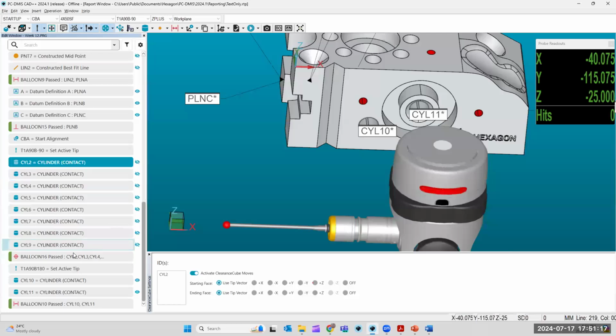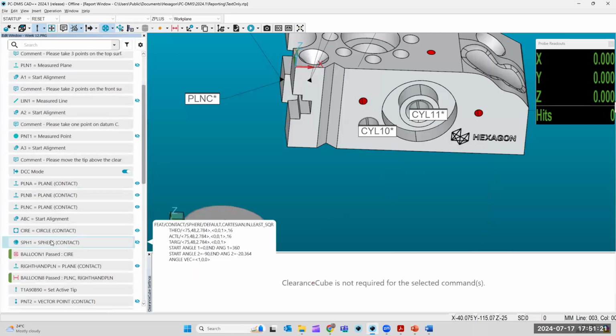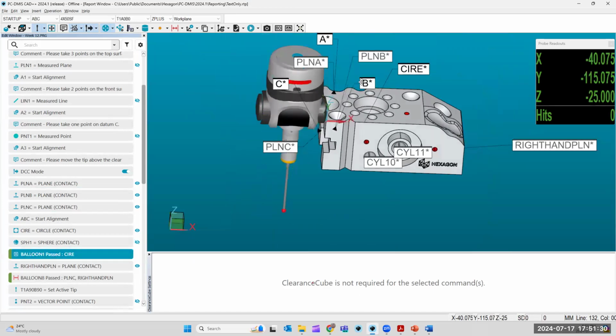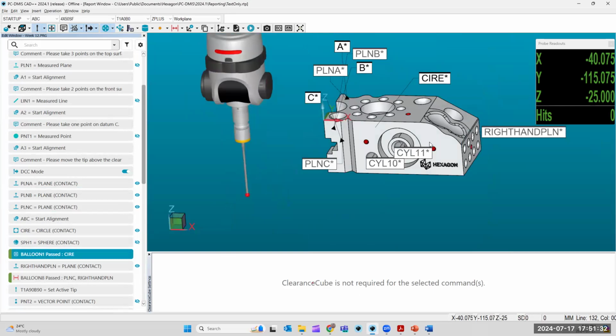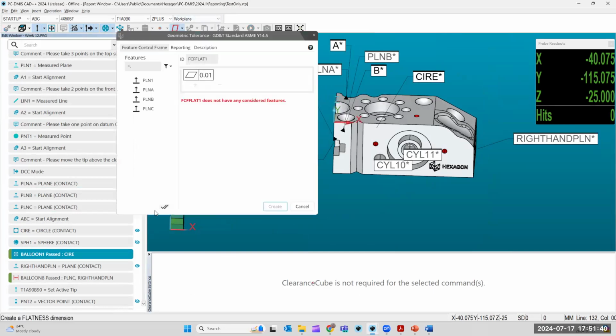You do need to have the capability of building an entire routine with a GD&T component. You must know, for your lab, how to do a datum label and how to measure some sort of GD&T feature. The simplest of which is flatness, because there are no dependencies.